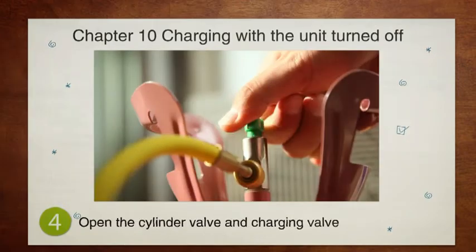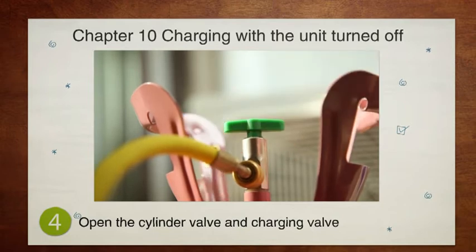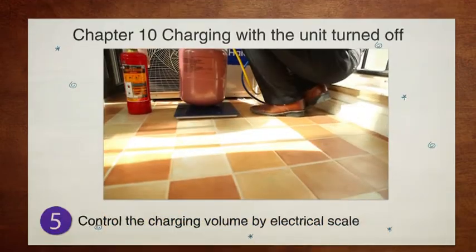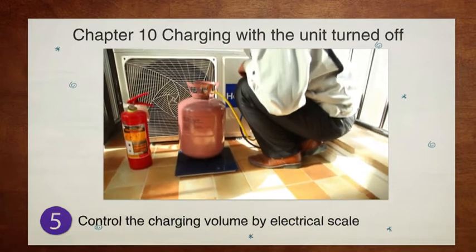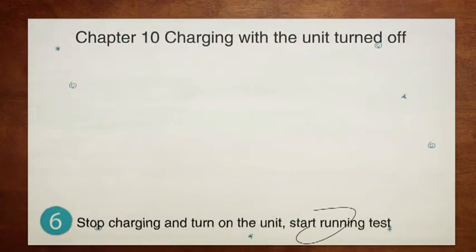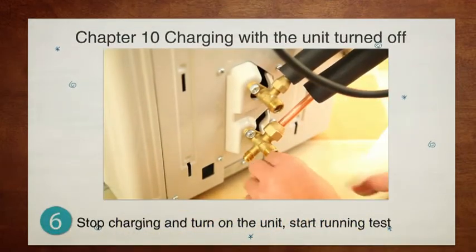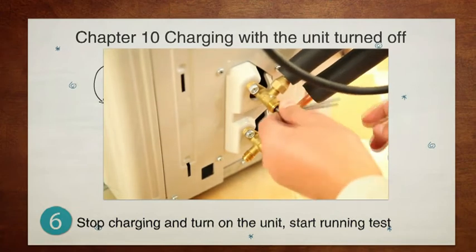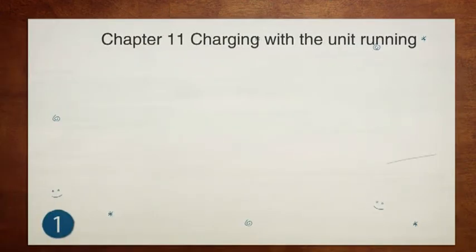Number 4. Open the cylinder valve and charging valve. Number 5. Control the charging volume by electrical scale. Number 6. Stop charging and turn on the unit. Start running test.